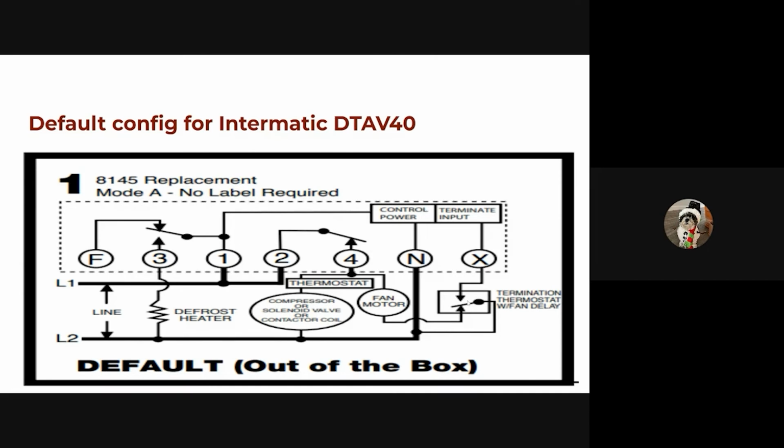I've seen that referred to as the drip cycle. And why do we think that might be called a drip cycle? Anyone who is actually in refrigeration might be able to tell me better. The drip cycle is when defrost is terminated, and it can be set anywhere from 1 minute to 5 minutes to 10 minutes, to allow the evaporator to drain all the water off the coil before refrigeration is initiated again, to keep it from icing up.